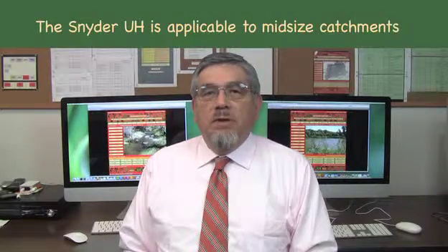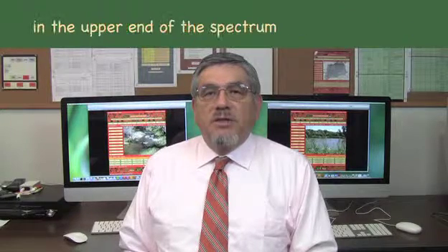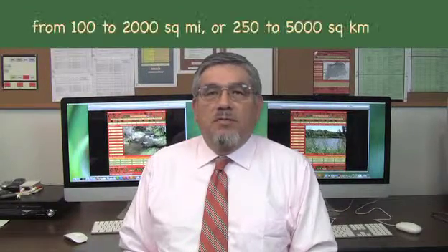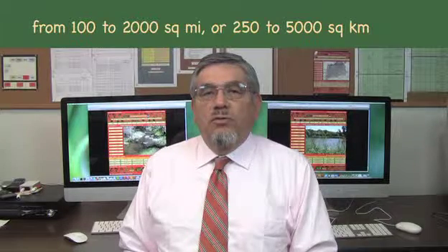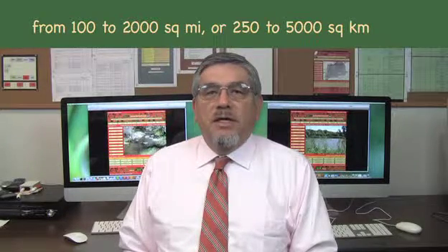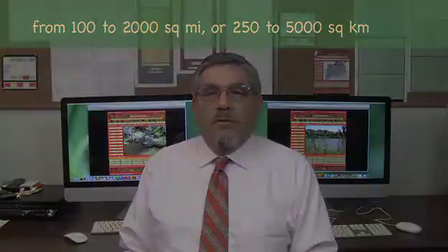Thus, the applicability of the Snyder unit hydrograph is extended to mid-sized catchments in the upper end of the spectrum, from 100 square miles to 2,000 square miles. That is, from 250 to 5,000 square kilometers.